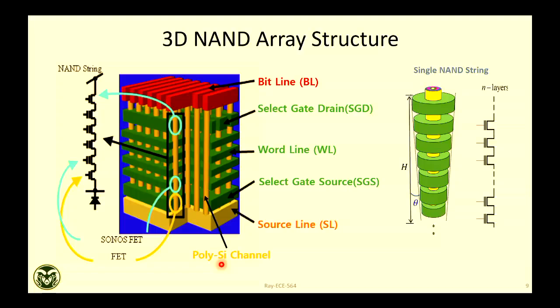Anything else? Yes. Basically, the silicon layer is typically pure silicon. But because of 3D NAND, it has to be grown. It's not as pure. So you are limited by the process. Yes, definitely. From a device physics point of view, we want crystalline silicon, but the process doesn't allow that. So that's the limitation, and that's where the challenge came.